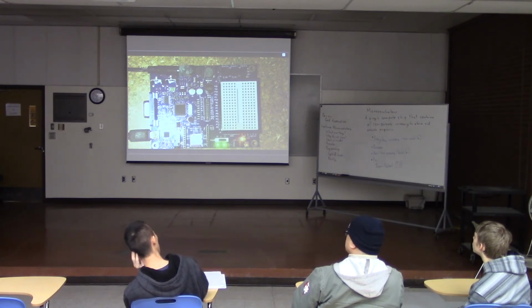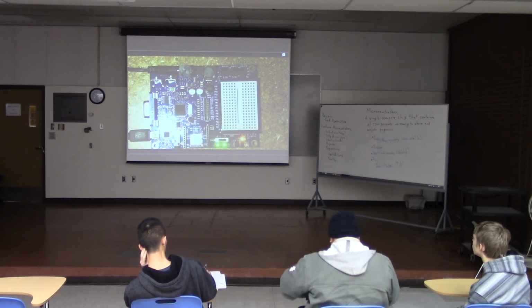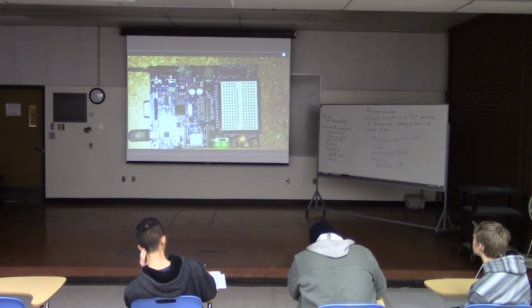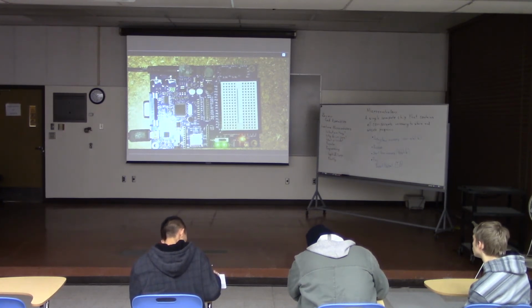So this is helpful if you are trying to program a robot that is on wheels. So if you're trying to do that, you usually put it on position 1 and send the program over, and then disconnect it from the computer and make sure that it's ready to go, and then switch it over to position 2 so it starts running.